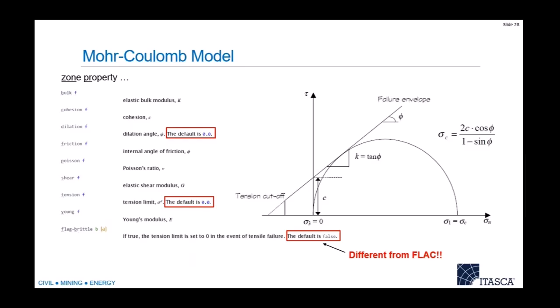So probably you have an intuitive feel for cohesion and friction of materials. I'm guessing I don't need to go into a lot of detail here. At a minimum, really, you need the cohesion and the friction, and the Young's modulus and the Poisson's ratio. So to use Mohr-Coulomb, you really need 4 parameters. Most of the time, you probably want to specify a tension cutoff as well.